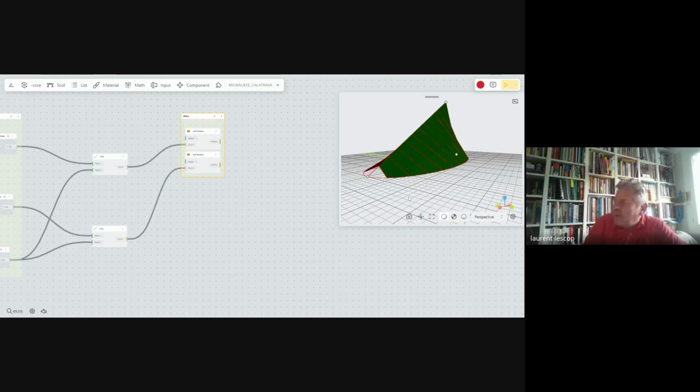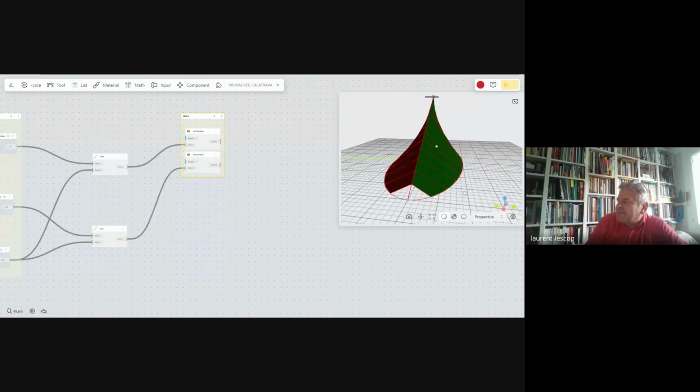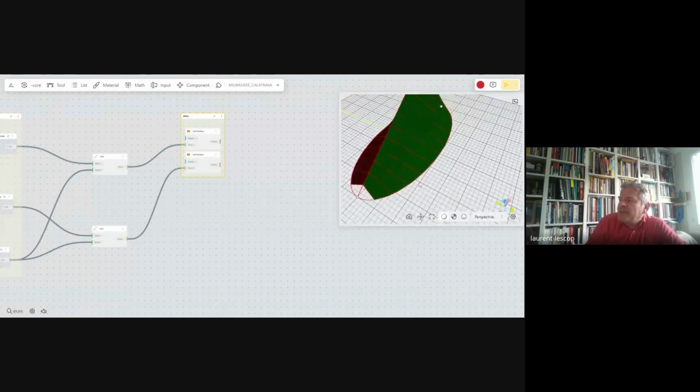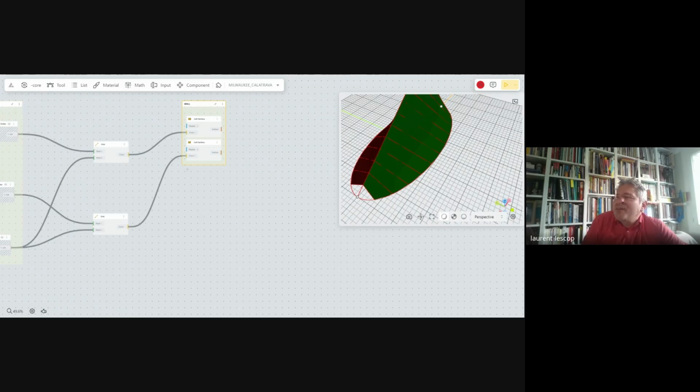You remember that we've got to open up the wings. For that, we need a rotation. So we will go into new problems using rotations. We'll see if it works or not, because first I had some problems, but maybe today I won't. If I don't know precisely where the rotation is, I just click and search rotate. I've got many, so it's not vector, it's not plane, it's going to be rotate here.